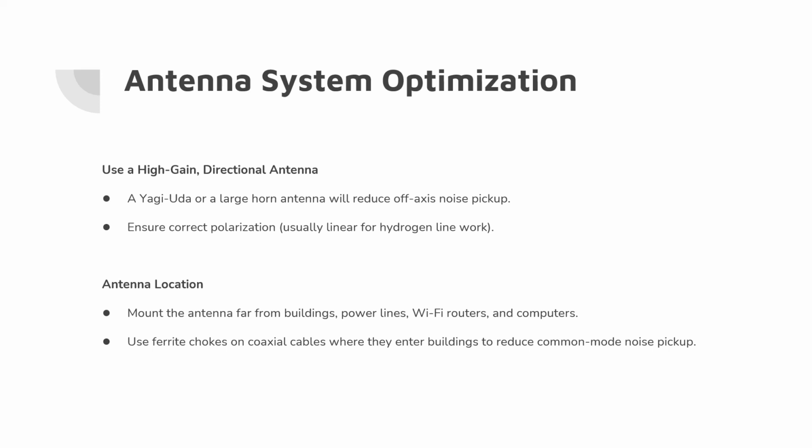But anyway, the RFI survey: pointing one of these little, not necessarily a Yagi, it's this other thing called a Logi, a log periodic antenna, so for wide bandwidth, and just a small one, handheld, with my SDR, swinging it around the 1420 frequency. Boy, anything pointing towards the south, slightly to the southeast, is just a raucous bunch of spikes, and things just popping up all around that frequency. So my RFI environment is just really, really bad. No correction for that, other than just go somewhere else to do my observations, which is not practical.